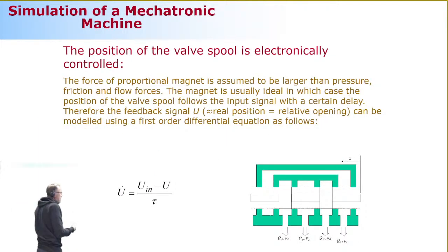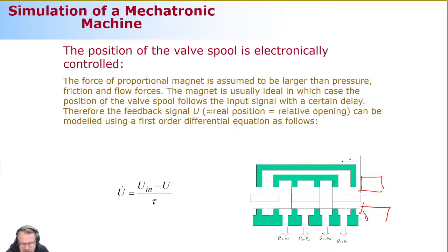Back to the modeling. How do we do the modeling of hydraulics? First step is this. We need to know where the spool is located. Most common spools and the valves that are currently used are the ones that are magnetically operated. So it goes like this: when we look at these forest structures, you have this joystick. A joystick sends a signal to magnets. A magnet is moving the spool correspondingly. So actual motion is conducted by magnets, which quite rapidly move this spool back and forth.